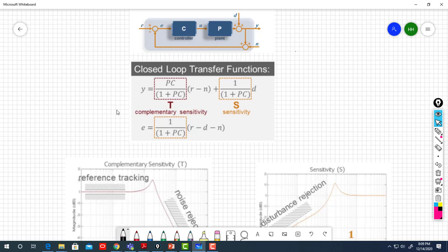And if you get the transfer function which relates the error over the reference input, or disturbance, or n, you'll find they are the same transfer functions with a minus difference. So if the output that I'm interested in is the error, and I have 3 inputs in my function, my output of interest now is not y, so I want to compute for e.